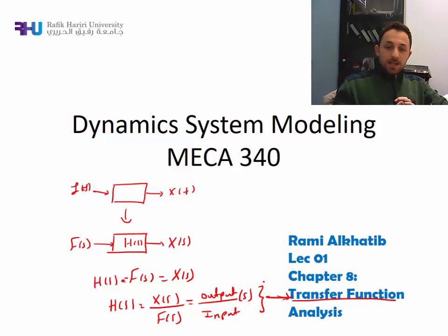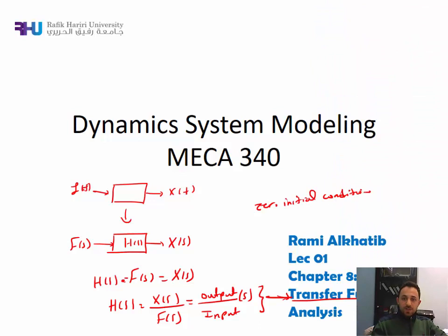Most importantly, remember, in order to derive the transfer function you should be assuming zero initial conditions. So your analysis of the system must start from rest, and you will not assume any energy previously stored in the system.